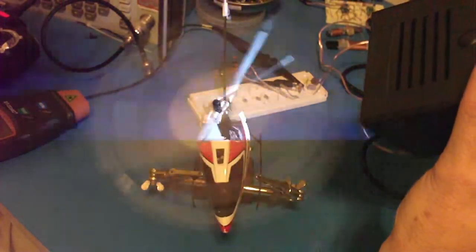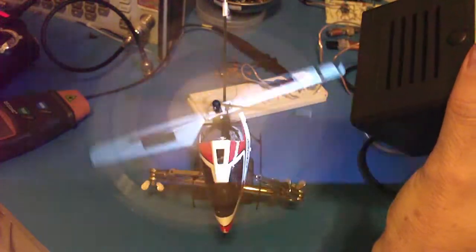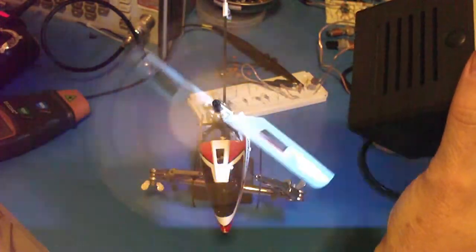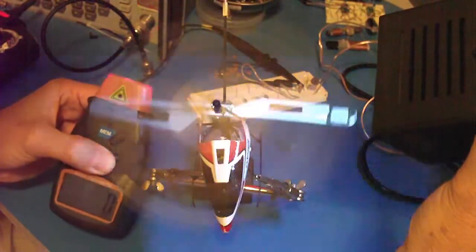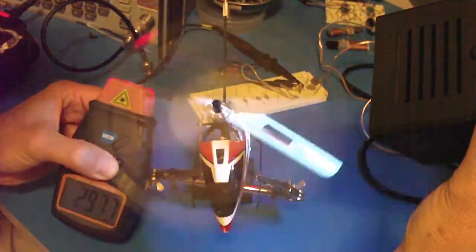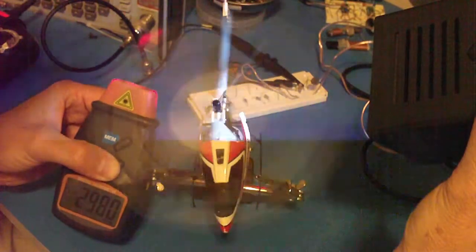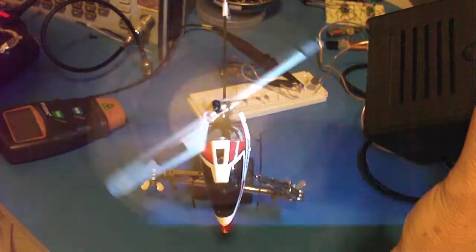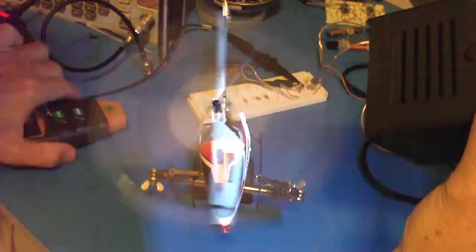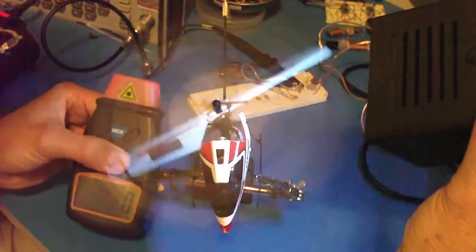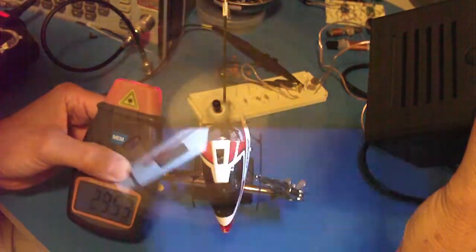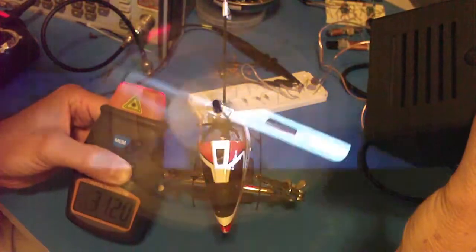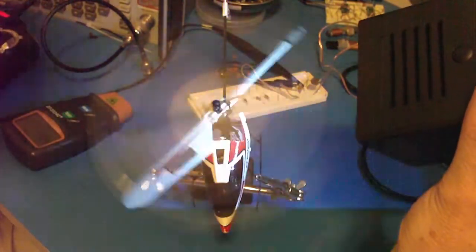So we start out and we get this low RPM, and we're expecting at 1500 RPM that we can see a reflector on only one blade, the other blade's bare, and the counter should read 3000. It's reading a little bit less than that, and that's why it looks like the blade's rotating slowly backwards. So if we speed it up a tiny bit, it should read a little higher than 3000 RPM, and sure enough it's 3107, 3106, 3113, and that's why it looks like it's spinning forward fairly quickly.